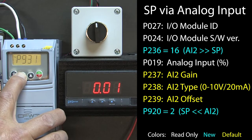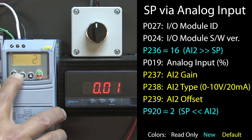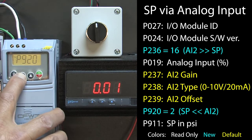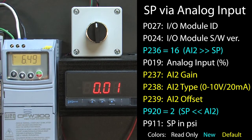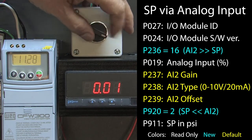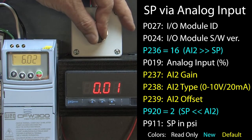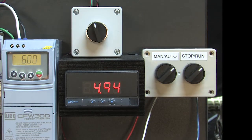Let's go to parameter 920 to tell the PID application to retrieve the set point from analog input 2. Now if we go to parameter 911 to view the set point in engineering units, we can verify that the PID application sees the set point and it's at 6.49 psi. We can vary that over the range, and let's start out right at 6 psi. Switch to run. And sure enough, the PID application adjusts the motor speed to get the system to 6 psi.